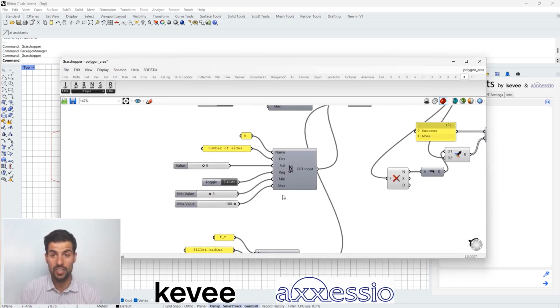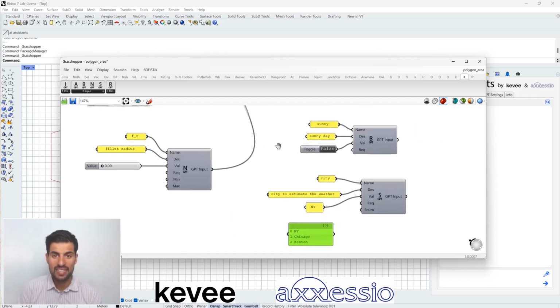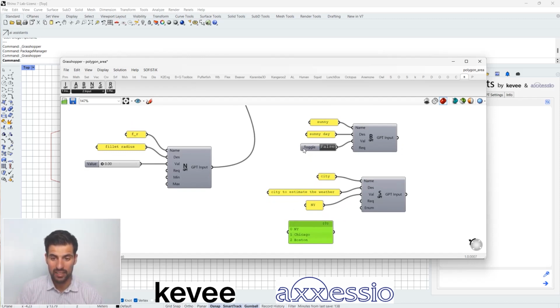Then in case of number input parameters, you can also specify a minimum and maximum value. In case of the sides, of course, I have a specified minimum of 3, which could be a triangle, and a maximum value of 100, because why not? And they are not part of this example, but I have just isolated these components here so that you can see how to use Boolean and string inputs.